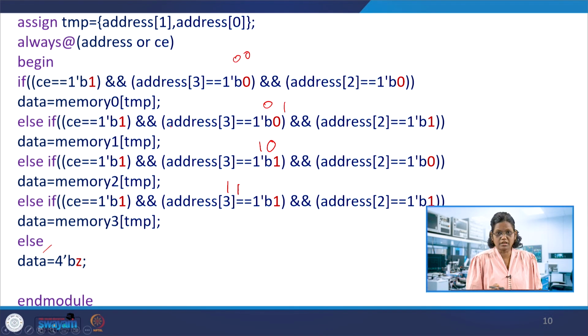The other one is the assign ternary operator. In the synthesis process, we would learn what structure it will realize, whether it is an if else statement or the conditional operator. If the conditional operator has mutually exclusive conditions, yes, it will go for the mux structure. So the hardware equivalent of this conditional operator will be the mux structure. If this condition is true, then go for this, else that.